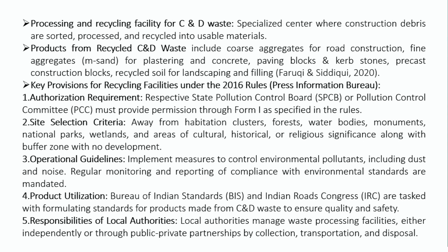Processing and recycling facility for construction and demolition waste: a specialized center where construction debris is sorted, processed and recycled into usable materials. Products from recycled construction and demolition waste include coarse aggregate for road construction, fine aggregate for plaster and concrete, paving blocks and curb stones, precast construction blocks, and recycled soil for landscaping and filling.